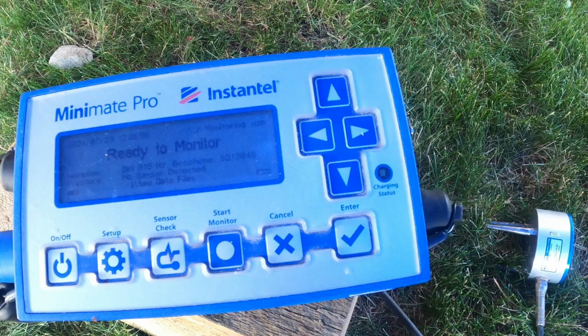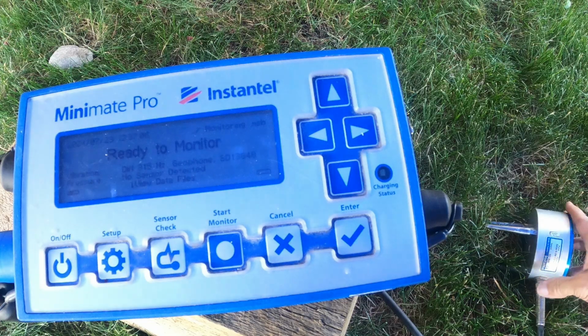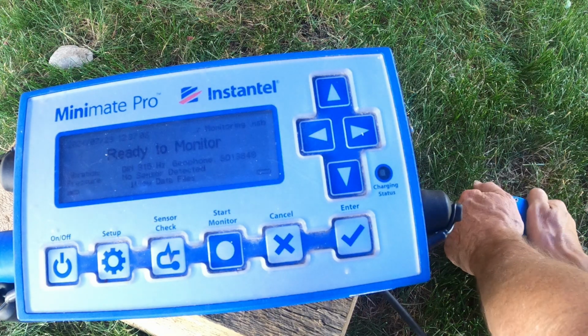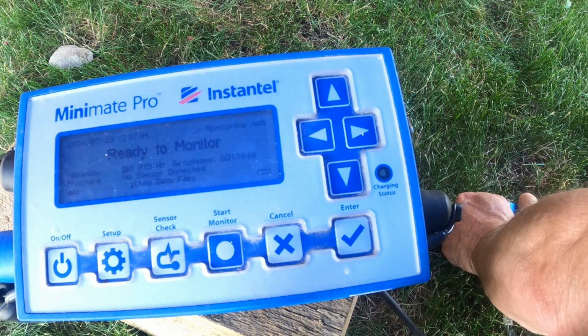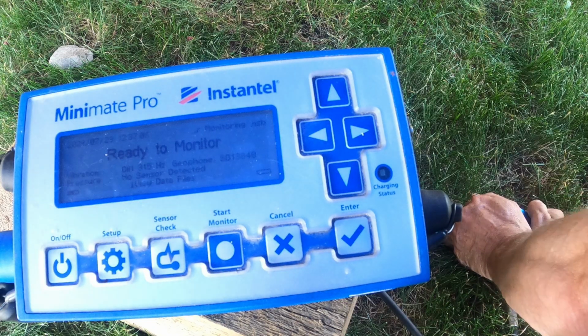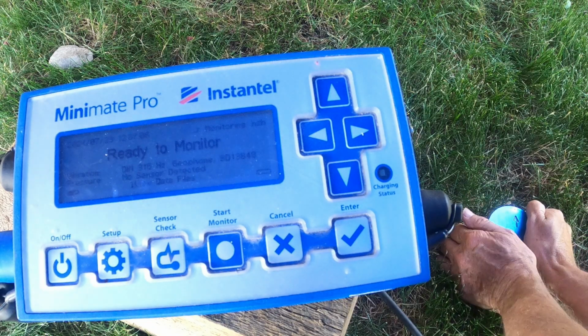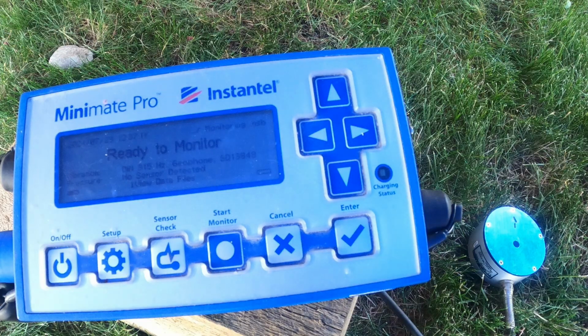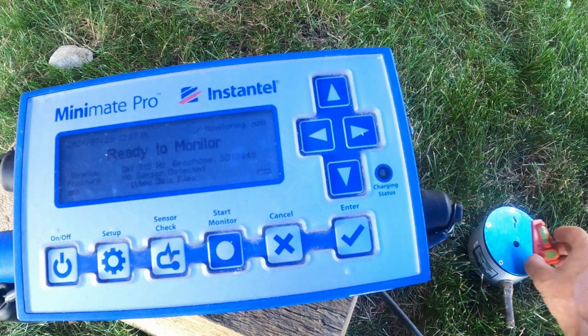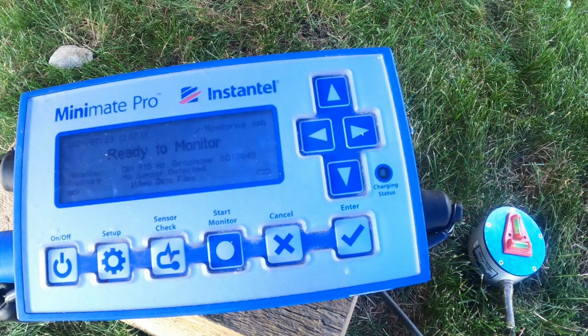Okay, I'm just going to do a backyard demo as to why getting the sensor level and having your sensor check protocol correct is so important. So if I am just going to install this instrument in my backyard and aim the longitudinal axis towards the source point, I may do it like that. But it's fairly hard to get the level or the sensor correct unless you're using levels.